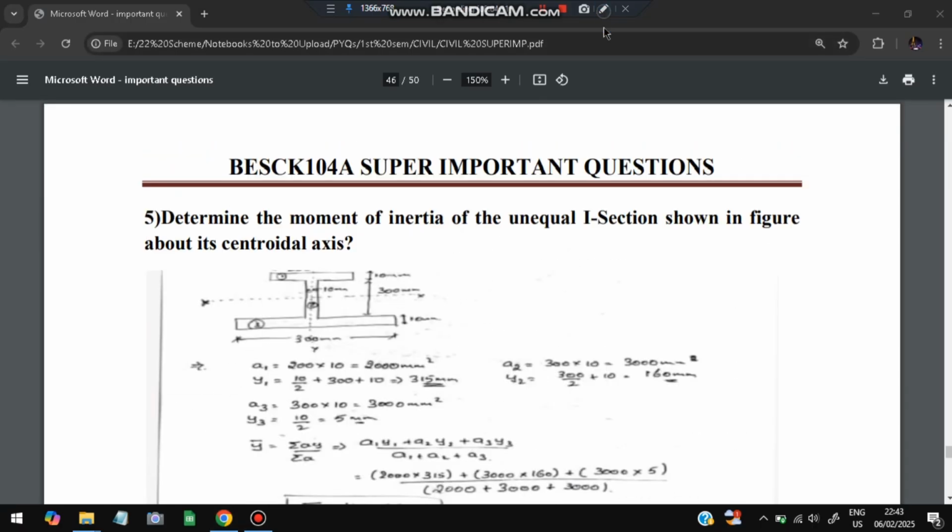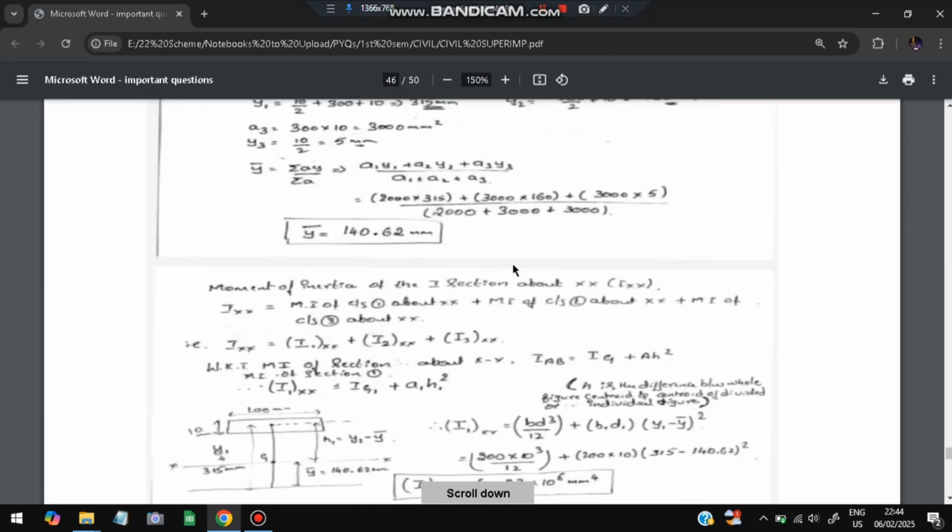Okay, this is the Ix6 value. This is the Ix6 line. From here, what is the moment of inertia for this diagram, this diagram, and this diagram, diagram 1, 2, 3? So it will be Ix1, Ix2, Ix3. That will be adding it up, so that we will get the Ix6 value. So Ix6 will be I1x plus I2x plus I3x.